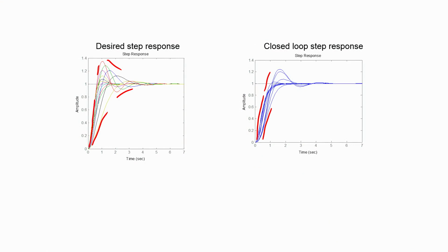If on the other hand, this spread that we see here in the closed loop step response for this particular controller is found to be too conservative, then we can go back to the controller structure and fine tune it a little bit in an interactive manner using the QFT toolbox, so that the loop gains at each of the frequencies lie almost exactly on the particular bounds at those frequencies, and hence we would have a closed loop system that just satisfies the desired performance specifications.